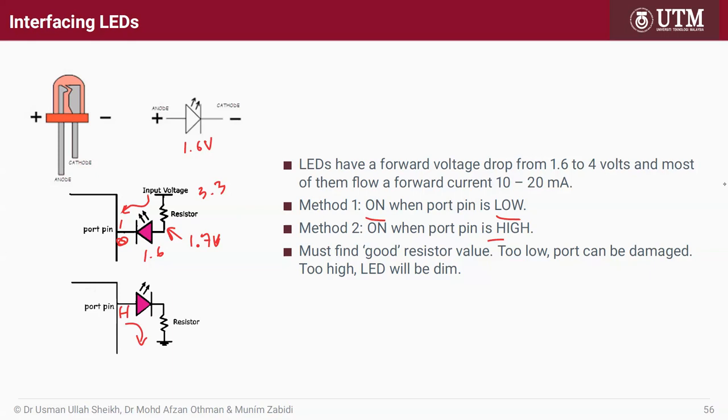But now many microcontrollers have good output current, and they allow the second type. But make sure your LED is a high efficiency one, or one that doesn't require so much current, because the current here is limited. If the LED is small, no problem, but if you have a big LED with high current requirement, you have to choose method number one.